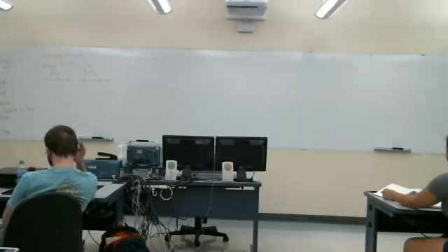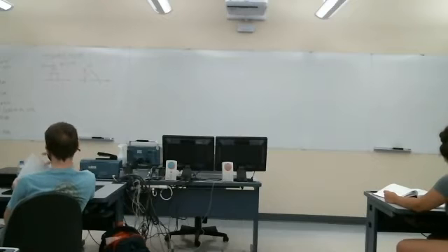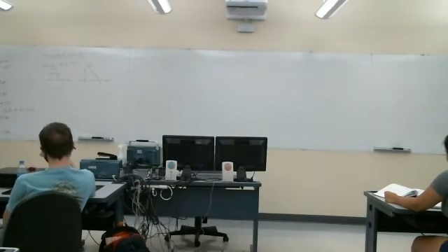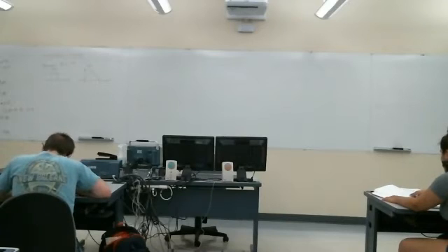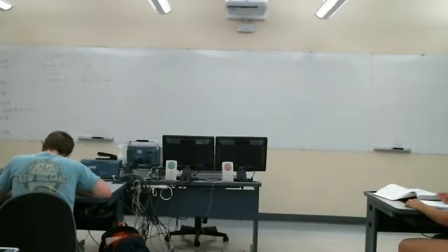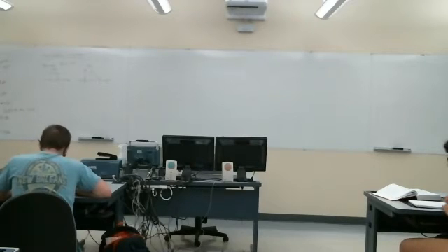Now, our tau is our dummy integration variable here. So we want to redraw these as a function of tau. My recommendation: you're always going to have two functions. In the integral, we've got to time reverse and shift one of the functions. I find it always easier to time reverse and shift the simpler of the two functions.